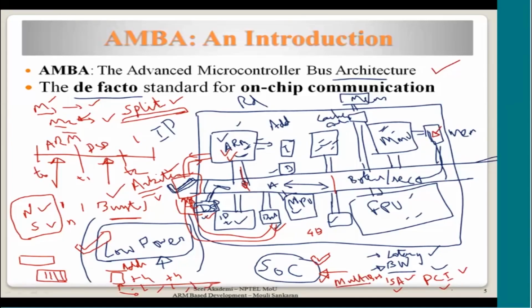We plug in some PCI based add-on cards to communicate with the motherboard of the PC, and Multibus is something like a backbone, kind of a rack. On the backplane there are the address bus and data bus, and then the cards go into the rack. So this is a kind of bus standard which was given by Intel.